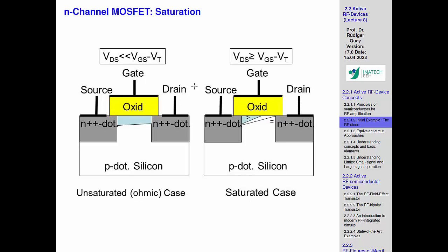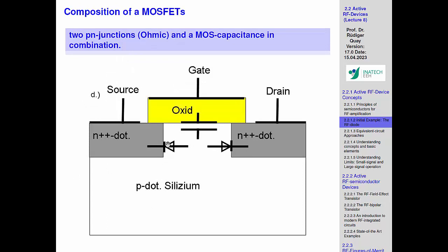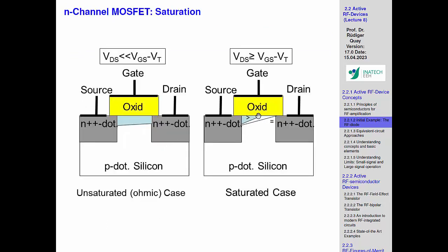If you pull hard on the source to drain voltage, then there will be a depletion here. And that is quite easily understood because the inversion is created, but the carriers are sucked out. And if there's a replenishment, so to say, this is one way of expressing it, then by the order of the gate voltage, you could activate that again. So you are reflooding something which is generically off. We are flooding this channel from the side, so we can very nicely control that.